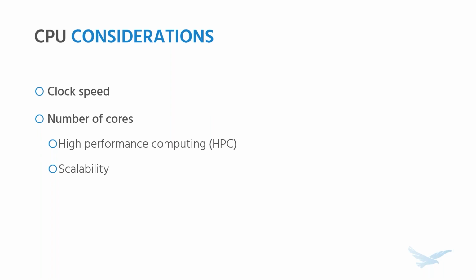There are even cases where the scalability is so poor that the additional overhead to split up the problem makes the solve time longer, where it goes from 60 minutes to 65 by breaking it up further. And so that's probably the most important consideration when you think about adding more cores is it going to be worth it?